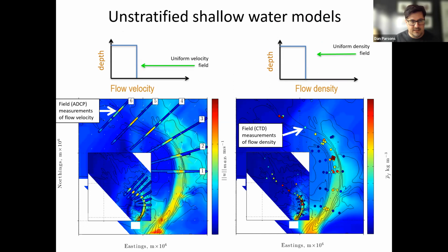And we can look at all of these sorts of field data. And then we can also use Rob Durrell's shallow water flow model to look at the patterns as well, and then start playing with a series of parameters where we could change the stratification and look at the sorts of patterns that resulted, where the fluid moved to, its shear stress, and where it may or may not then deposit sediment should these flows be sediment laden. We were using the salinity here as a proxy for sediment.